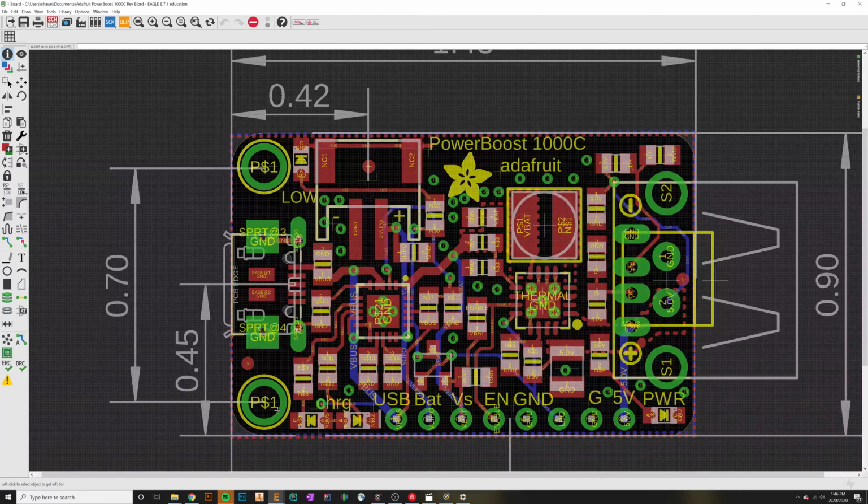So I'm going to place two of these down, and I'm going to use the info tab. If I click on this, notice that the units are still in millimeters. So I need to go back and change the grid line to inches. Okay, I'm going to hit OK, and I'm going to click back on this again. And I'm going to change those positions to what I had noted before, so 0.1 and then 0.8 for this top one. And for the next one, I'm going to make this 0.1 by 0.1, just like that. Okay, so I'm pretty much done. I have each one of the holes that are on this board here.